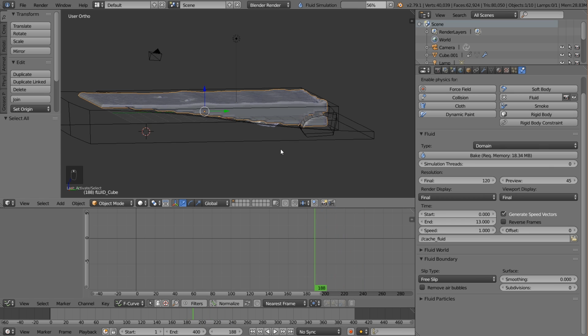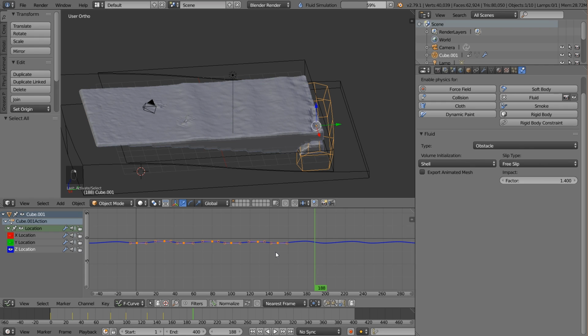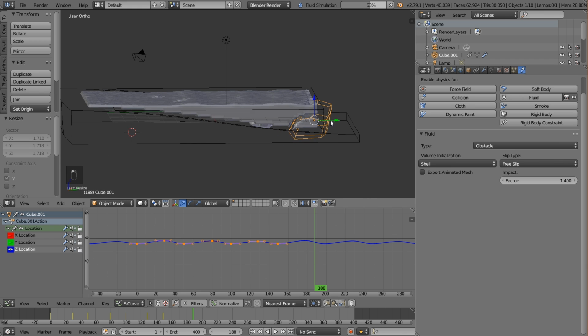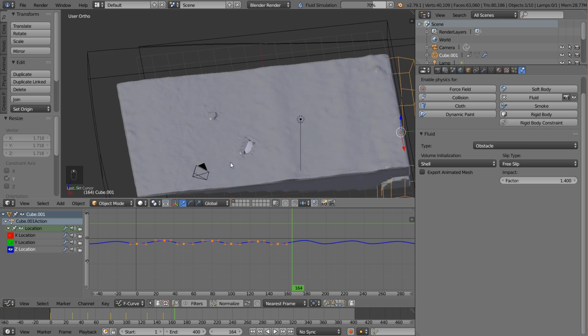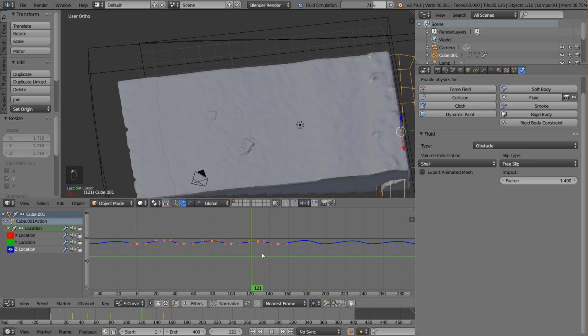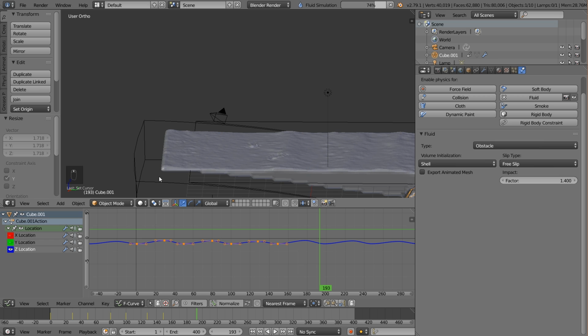Just some nice gently flowing waves, and we can increase the height now a little bit more if we wanted, just to make it a little bit more intense now. And possibly pull everything down a little bit. If you feel like it's coming up too much and causing splashes, then you can grab everything along the y-axis and move it down. But I feel like that's going to be pretty good now that the water's a little bit deeper. And we can also see that the shoreline here is looking a little bit better. It's a little bit leveling out here.